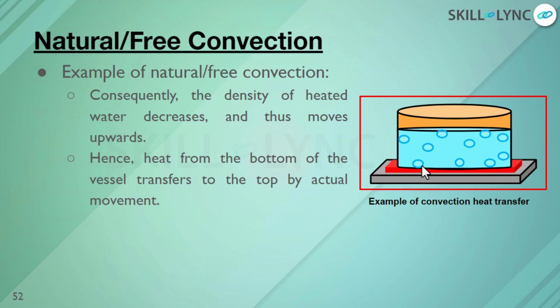As they get heated, their density decreases. Thereby, it allows them to move upwards, and while they are moving upward, they carry the heat with them and thus transfer heat to the other water particles through convection. This happens due to the difference in densities. Therefore, it is called natural or free convection.